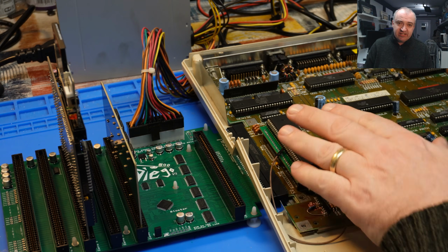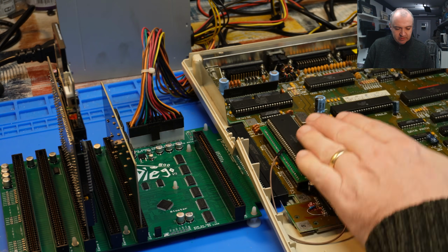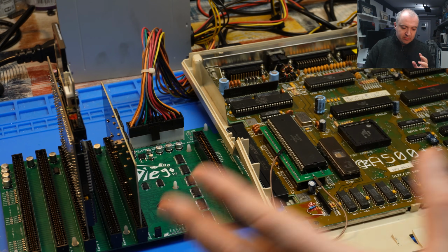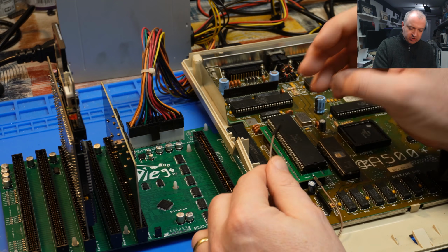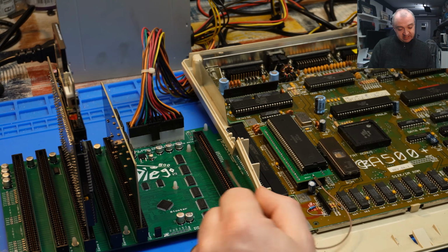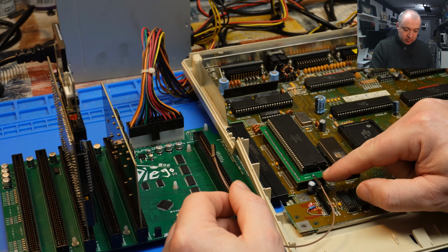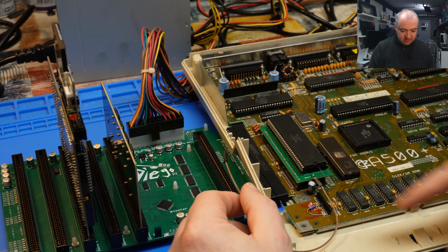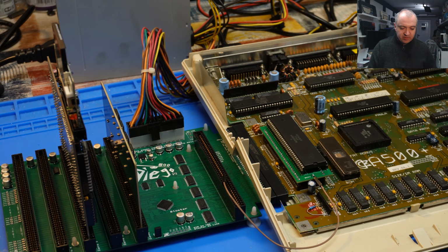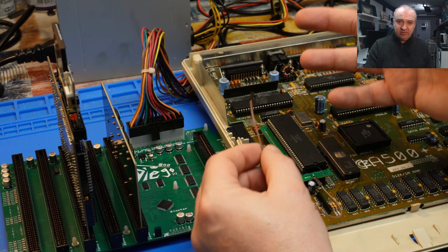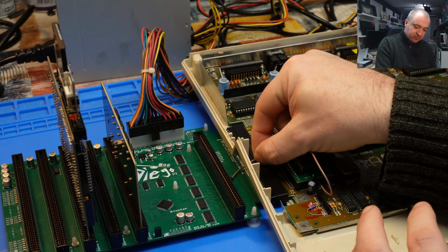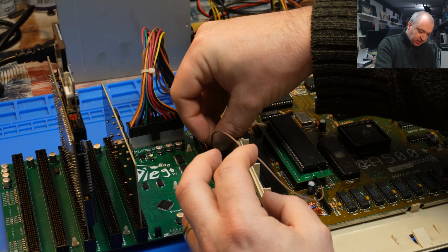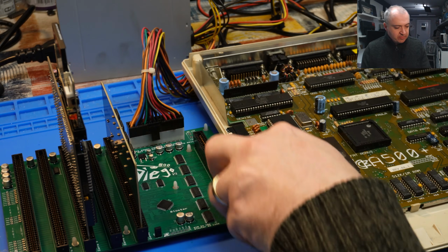My original intention for this was to make it one of those L-shaped things, so that you could use one of the accelerators in here as well. I might just revisit that idea. But for now, we're not worried about it. I don't need the keyboard just for this testing. And just looking at this, the other thing that I might do is move that point for the BOSS signal connection to the other end, just because here it is a bit close to that capacitor. Ultimately, when you're fitting this in your case, you'll need to run that wire through there underneath. But for now, since we don't have the lid, I'll just attach that on the top side.